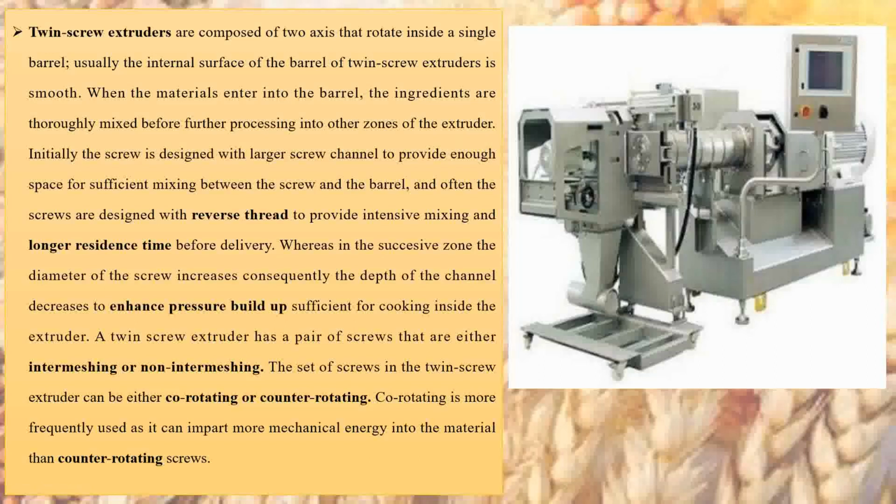Another advantage is that this twin screw extruder can be operated over a large range of moisture content, almost 30 to 40%. In the case of dry extruded products like berries, nuts, drupes, or cereals and pulses, we can add water externally or supply external moisture in the form of a solution or any chemical solution that is needed, by mixing in the additives or seasonings or whatever food additives we want to meet the requirement.